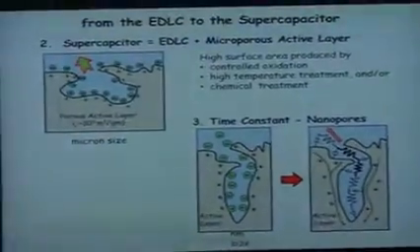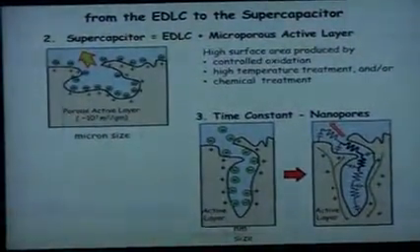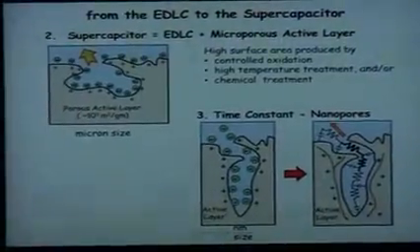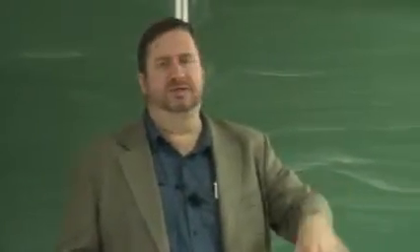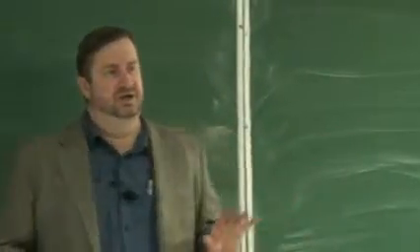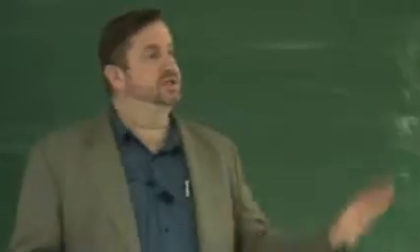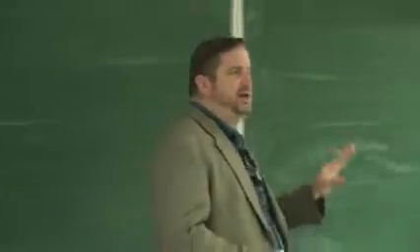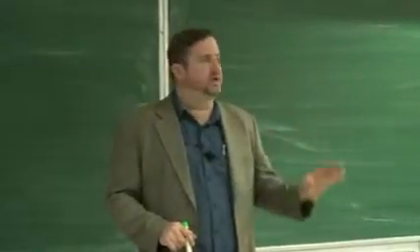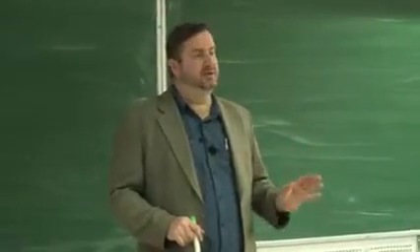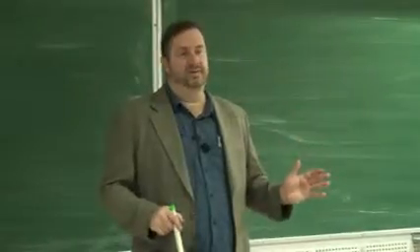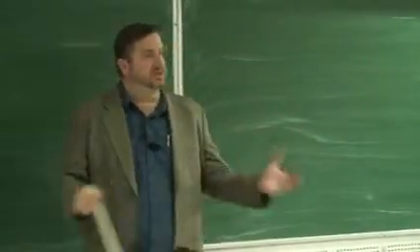You also, in making a high surface area material, you have to recognize that what you're also doing is creating channels for charge transport. That's good in one way because every extra channel that you make is more surface area, but it also introduces some resistance to the flow of charge. And so it's not all good because resistance is something we don't want. As soon as you send current through a resistor, part of that energy is going to transform itself into heat. And then heat is not something that you can use in a useful way, right? In fact, it's just dissipated.